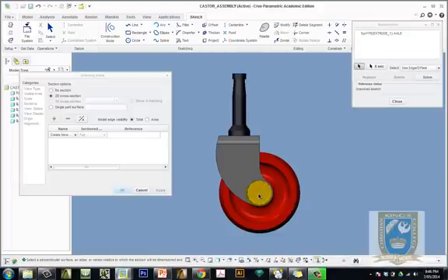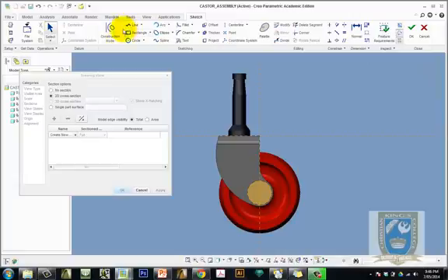That's enough to give me the center of that. While I'm there, I might also select this vertical edge and that horizontal edge, and that's probably going to do me at the moment, so I click on references. You'll see here I'm in the sketch mode, so it's asking me to sketch some lines to represent this offset section, and when I've finished the sketch, I'm just going to click OK.